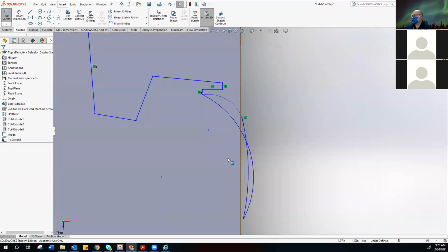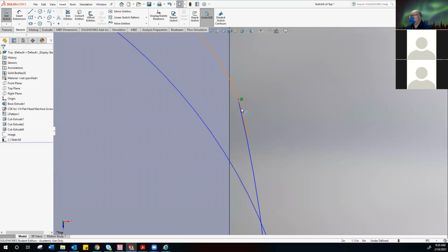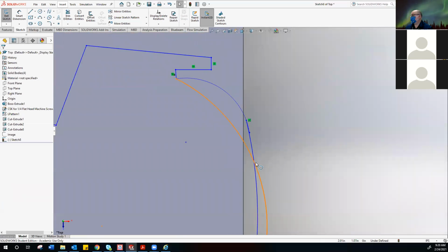And I can see this is kind of a mess. And I can't make a 3D object out of a mess like this. One, I've got these endpoints that are not connected, and I've got lines that overlap. So I can clean that up easily by taking that one out. And then I use a constraint tool to fix the other one.